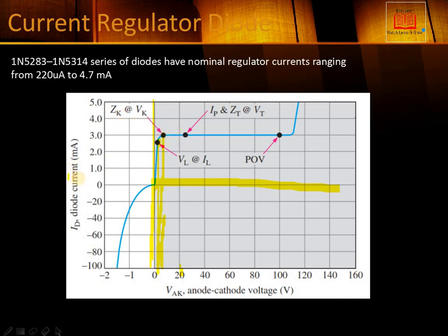Regarding the impedance, in the case of the current, you can see that the current is not exceeding. It means there is an impedance or a resistance, an internal resistance of the device, that tries to decrease or not increase, and tends to maintain a constant current. So it is almost a resistance in the way of current that maintains a constant current. So its impedance is really high, and it's mentioned in data sheets.